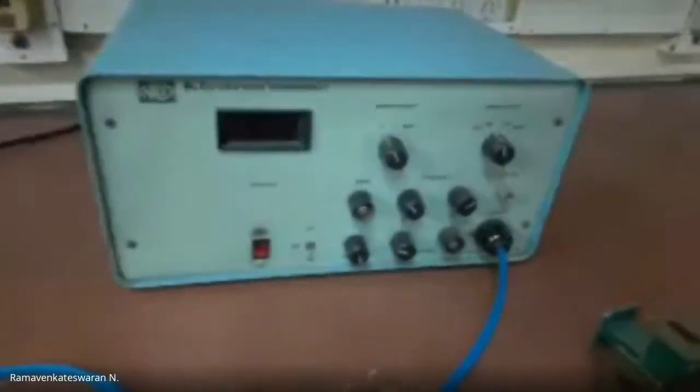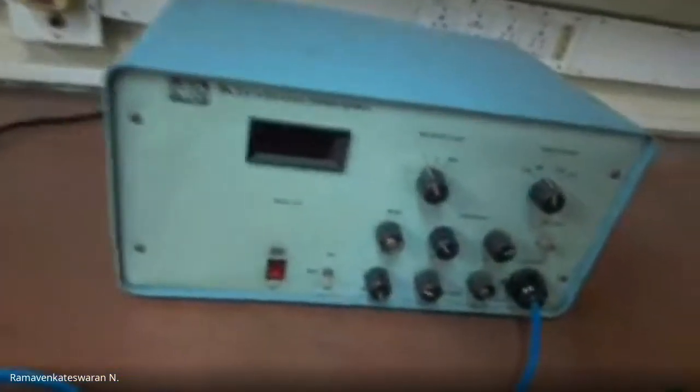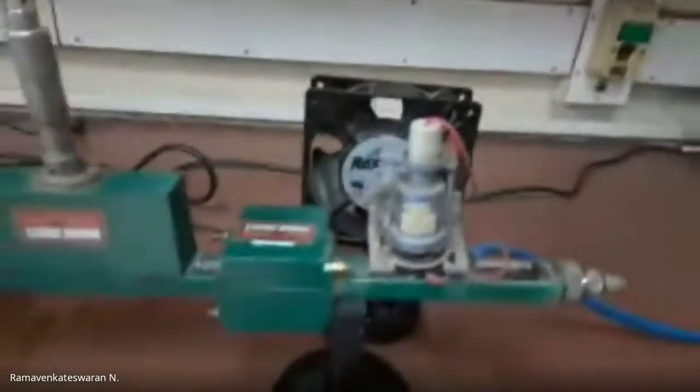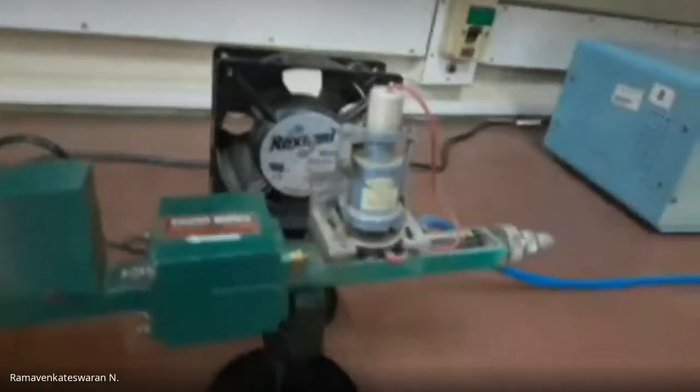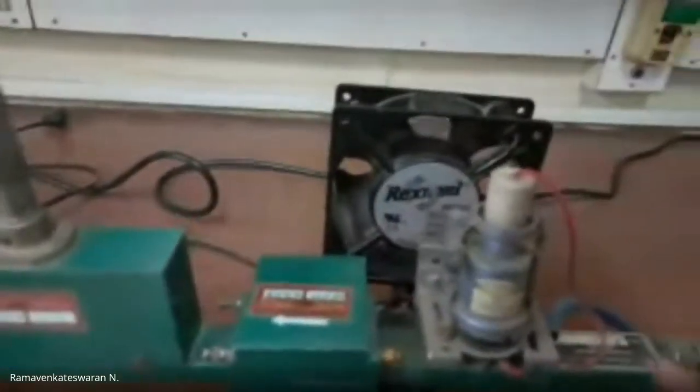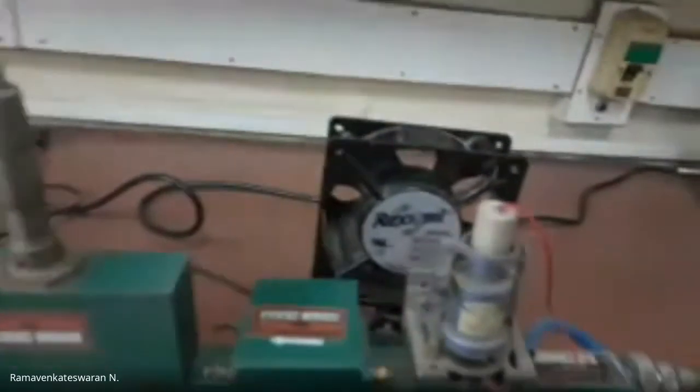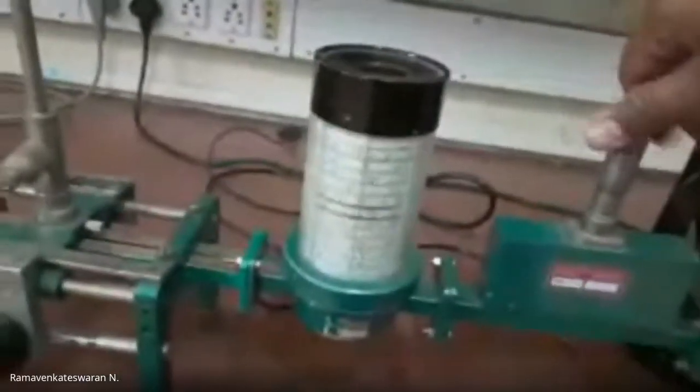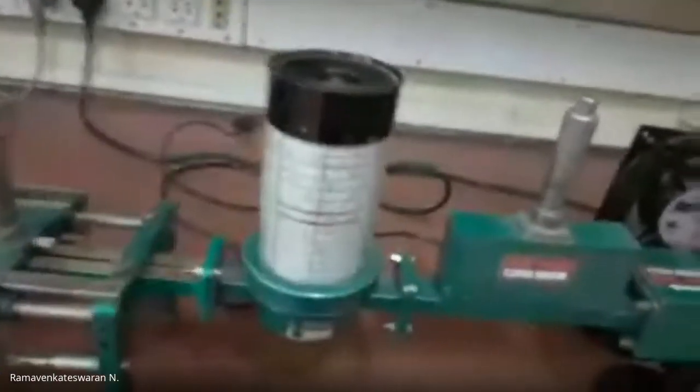As of now, just think that this is the RF power supply, which gives very high power to the crystal oscillator. You can see the company too, made in USA. It is an 8 to 12 gigahertz crystal oscillator. This is a crystal mount, used to generate very high frequency. Then it is connected to the isolator. After that, there is a variable attenuator, where we can control the power going to the test bench.